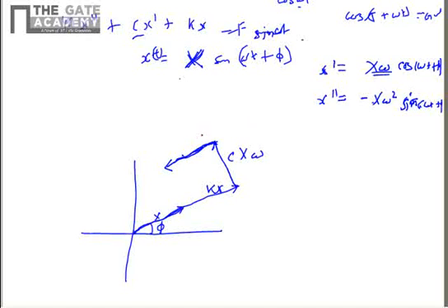The magnitude of this will be x omega square, and here x double dash will be x omega square, and then m is multiplied. So mx omega square. So you see that in all these cases we are talking about amplitude. Kx is the amplitude of this force, cx omega, and all of these are rotating in vector space with the equation of sine omega t plus psi.